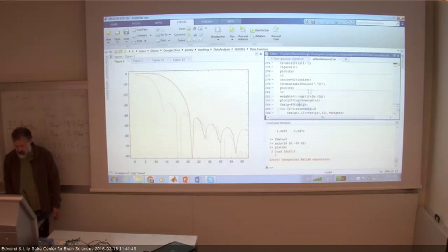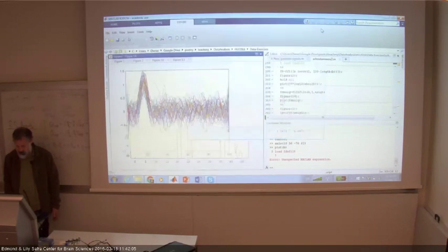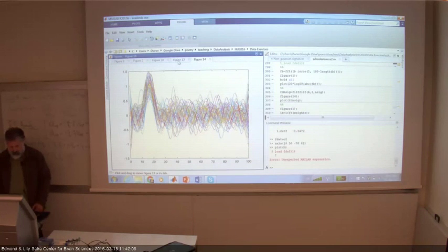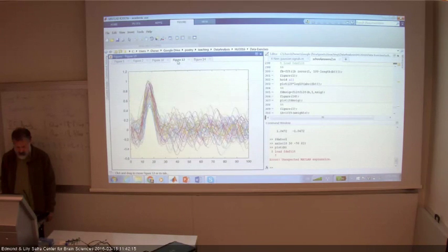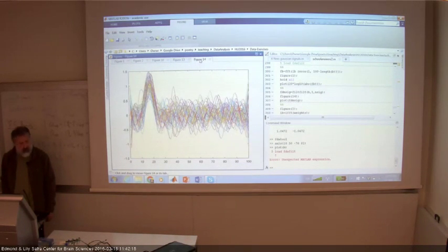And finally, last thing would be to filter. So here I filter. This is the result of Wiener-Hopf, and that's the result of my filter. It's not bad. They're not that dissimilar from each other. They reduce the noise to about the same degree. The signal is better kept here than with the Wiener-Hopf because the bandpass is a bit wider, but also I reduce less noise. The one big difference that you can see here is in the edge effects.